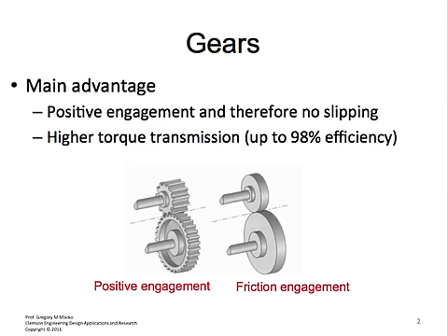So gears have teeth, as I've previously mentioned, because we don't want to rely just on friction in order to transmit power between rotating shafts. The teeth allow us to transmit more power without having to rely on the coefficient of friction and the preload from the shafts.